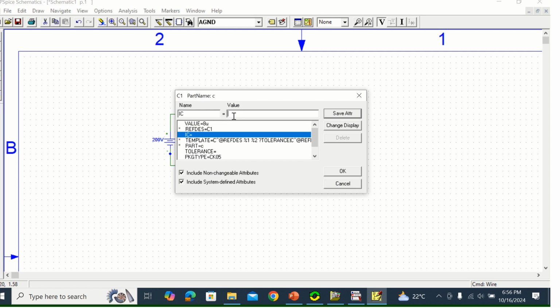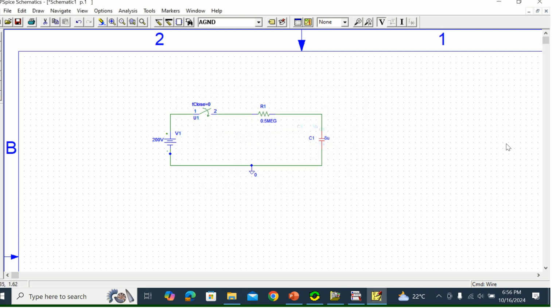Initial condition means the capacitor is initially uncharged. So the voltage across the capacitor initially is 0 volts. You can just type 0 or you can type 0V. Both are okay. Now I want to observe the waveform. We are interested in the voltage across the capacitor. So you can click this voltage marker and place it here. That means the voltage across the capacitor waveform will be displayed.